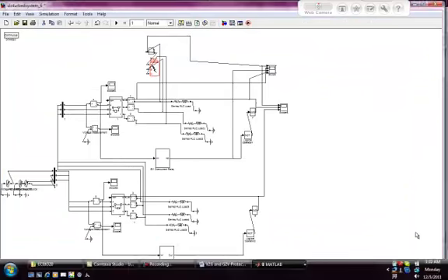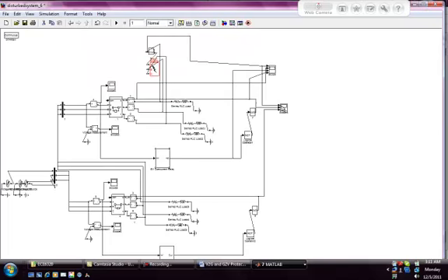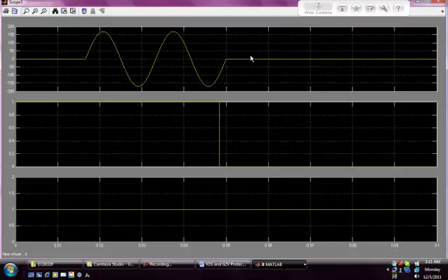The first scenario is the fault on the EV, or electric vehicle, circuit when the EV is acting as a load. The overcurrent relay, which is displayed here, uses a pickup current and a time delay. The first plot will show the overcurrent passing through the electric vehicle breaker. The second plot shows the breaker position of the electric vehicle, which trips at approximately 0.05 seconds. The house breaker will remain closed throughout the system, and this is what you will expect to see.